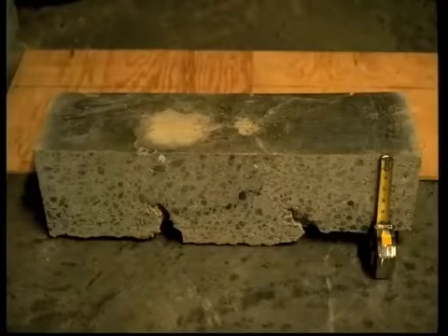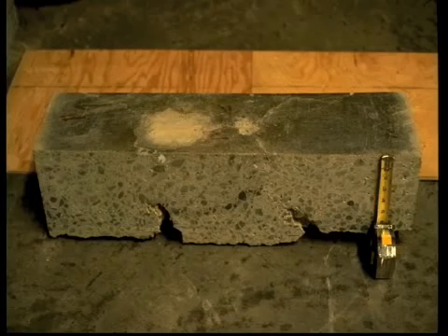The sand is displaced easily, and concrete discharged from a pump hose can push sand and cause sand ridges. These ridges look like contraction joints to the slab, and a crack will follow from ridge to ridge. So from the top surface, it looks like a random crack. This problem can be avoided by making sure that the sand is damp before placing concrete and that concrete discharged from a pump lands on top of existing concrete that has already been placed.